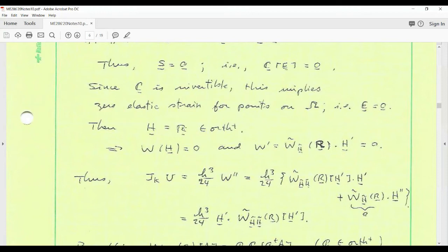It's not uniform. It doesn't have to be uniform rotation. If H were a gradient, which it's not, then it would be uniform. Remember, in continuum mechanics, you know that if the deformation gradient F is a rotation, then because F is actually a gradient of a vector field, you can prove that it has to be a uniform rotation. That's what gives you rigid body dynamics. The rotation is uniformly distributed throughout the body. Here, H, recall, is not the gradient of any vector field. So although it's a rotation, it need not be uniform.